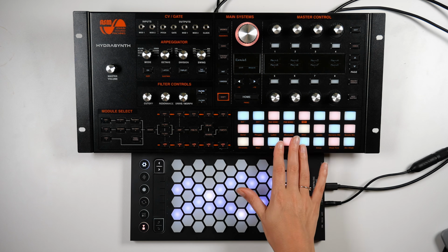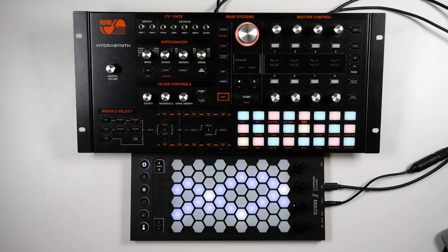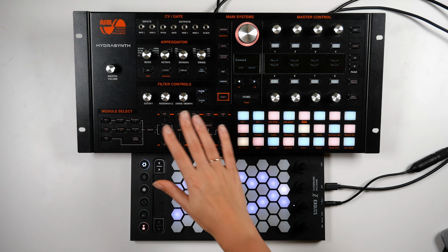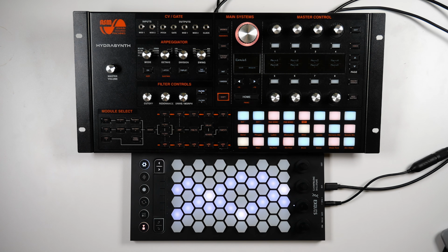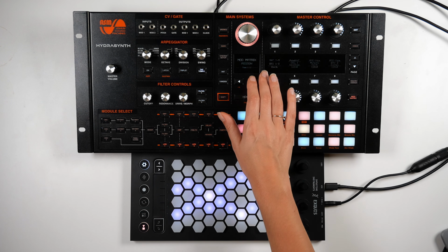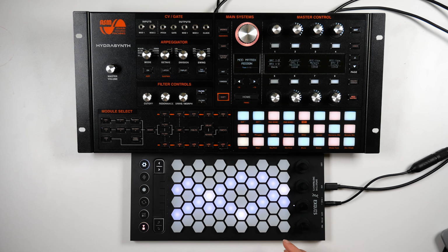One really cool thing about the Hydrasynth is that it handles MPE directly in its modulation matrix, which means that the routing for MPE data is super flexible and can be used to impact any of the synth's modulatable parameters. So in this patch, I'm using the pressure, the Z-axis, to modulate a parameter on Hydrasynth that's called wave scan, which is essentially going to interpolate between a bunch of different waveforms on the Hydrasynth. And then I'm using the X and Y axes to modulate pitch bend and FM depth, respectively.